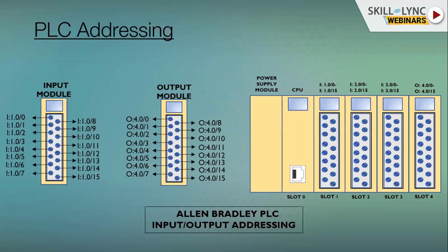Here actually 16 inputs are there. If it was more than 16, like 32 input points, then that 0 would be 1 from the 16th input onward. So that is subgrouping. And the last part identifies the exact input point. They are numbered in increment manner, 0 to 15.